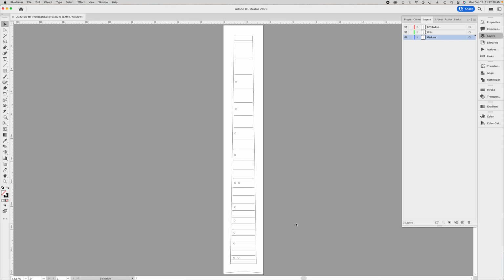There are several concepts which I think are important to understand with regards to how I set up my CAM strategies. When I create a drawing for one of the parts, whether it's the fretboard, the neck, or a body, I always make sure that those drawings are centered in a document that is sized to match whatever blank I'm going to be carving that part out of. So in the case of this fretboard, it's 3.5 inches wide and 22 inches tall. So the blank I'm going to be using will be the same size.